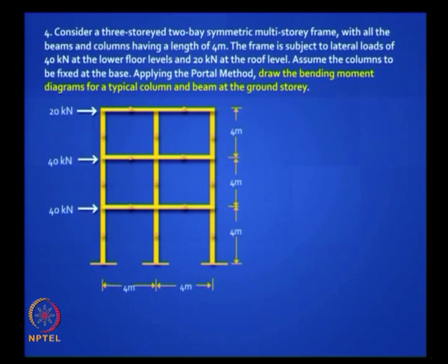Okay, first of all you have to get the story shears. We are doing portal methods, so these are the story shears. You don't worry about what's happening on top. Some of you insisted on solving the entire problem, finding the actual forces in the beams. Don't waste your time, and mine too.